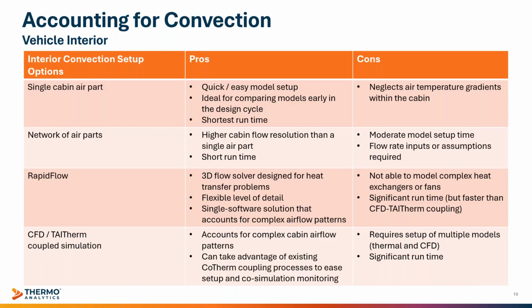Convection modeling is going to be important on the interior of your cabin if you're doing an HVAC heat up or an HVAC cool down simulation. There are a few different options available to you for convection modeling. All these options are valid. You just want to choose the one that gives you the result fidelity you need while balancing your runtime needs.